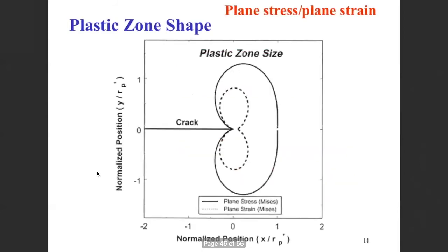But what you have is the crack here, and you've got a plastic zone size. This is for mode 1 opening, and it looks more like butterfly wings than circular out front. So this is where you're going to have plasticity approximated. Now this is where it gets weird.